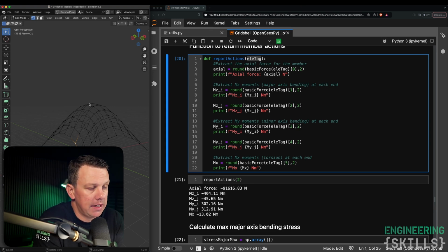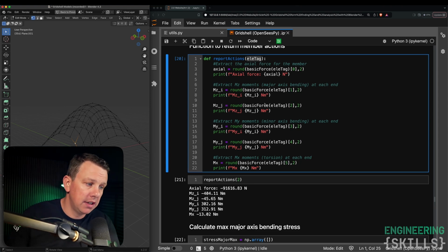Okay, that's a reasonable step forward. And so the thing to do, if we wanted to identify the optimal shape, the shape that experiences least bending, would be to generate a number of different geometries. How would we do that? Well, we just run the same Blender physics simulation and change the vertex mass in each one, and that would give us various different geometries. Then all we'd have to do is run the analysis for each of those, determine the bending stress in each one, and identify the one that has the smallest bending stress, and then you're done. Okay, so you've identified, according to your definition of optimal, the optimal structure, and that's the approach that we're going to take here.